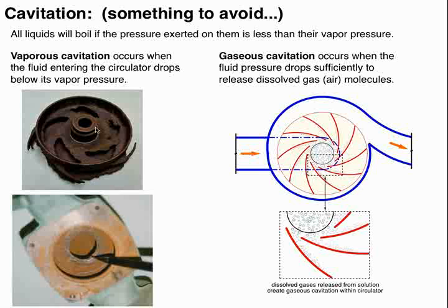where it boils. When water gets down to its vapor pressure, you instantly get vapor pockets forming, and that's not the damaging part. What happens is eventually the pressure increases, those vapor pockets implode. And if you've ever heard that, it sounds literally like somebody's taking a hammer and beating on the pipe. It's very noticeable. And those implosions are very violent, but at a very small level.